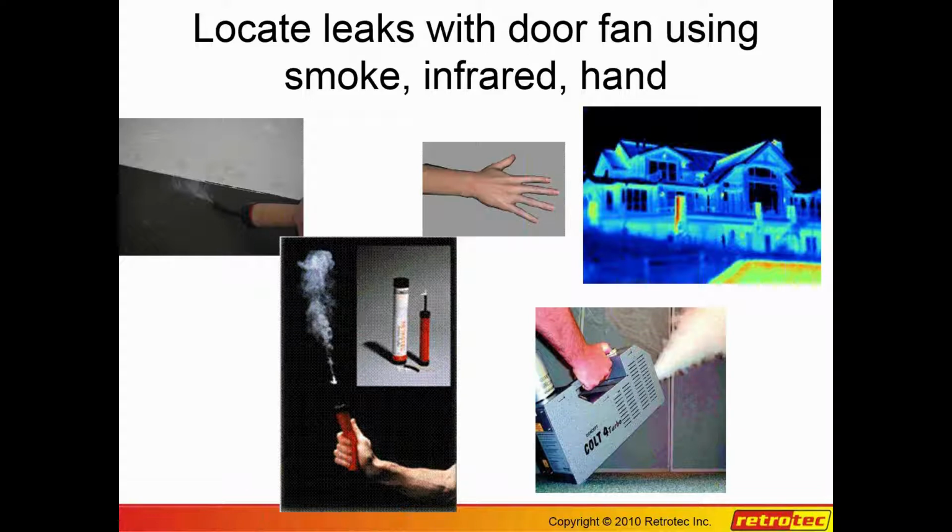Once you get that done and you want to look at individual components, then we would use a smoke like this, which is a neutral buoyancy smoke, titanium tetrachloride, unfortunately a little on the caustic side, and since 9/11, one that's impossibly difficult to ship. If you ship this, you have to ship it under a hazardous materials designation, and if you don't, you can be fined horribly. So I would suggest that if you buy these, you take that into account.